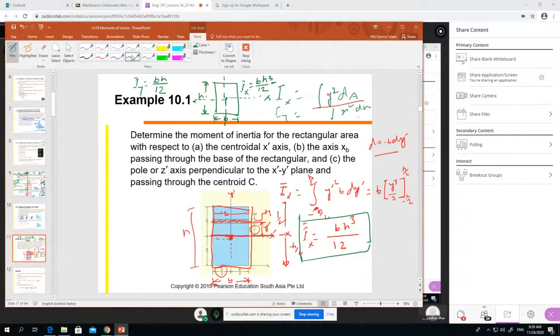So b cube. For now, you need to remember this formula. For remembering it, for x, the parallel is b. Parallel always has 1. You remember like this. For y, parallel is h, so h always 1, and the other one is 3. B cube by 3. So this is the formula for the moment of inertia of a rectangle shape through the axis, right?